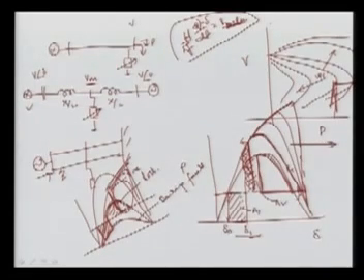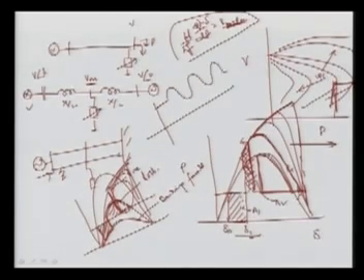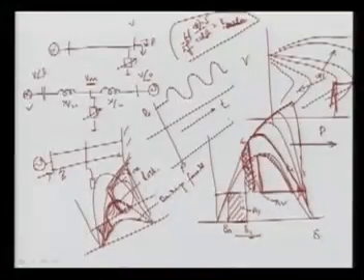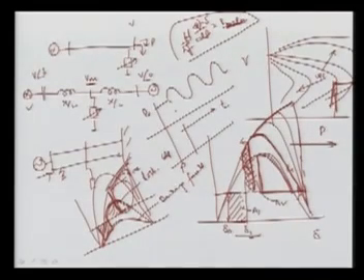So what happens? The power swing here is normally of this characteristic. Let's suppose your power is oscillating. This is, let's suppose, the power, and it started oscillating here. This was your P naught, and this is with respect to time. So this is oscillating. Now what we can do, if we can provide some mechanism for reactive power support from this point, means if it is oscillating we can inject more reactive power in the system, and if it is underdamped, then we can go for this.